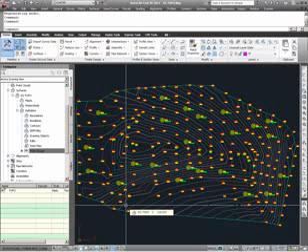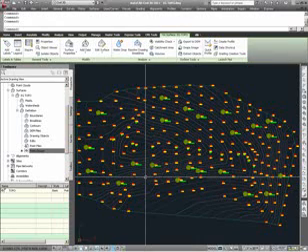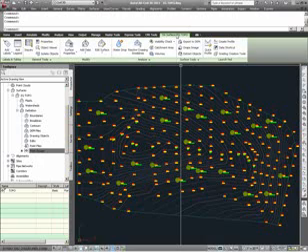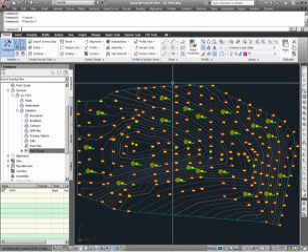As you might recall, the surface style was 2-foot and 10-foot contours for background purposes. In selecting the surface, I can further verify that it is in fact a Civil 3D surface by the fact that a context-sensitive ribbon now appears for a TIN surface called EG Topo. As I clear my grips and deselect that surface, that ribbon goes away.